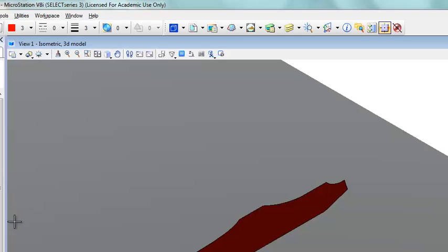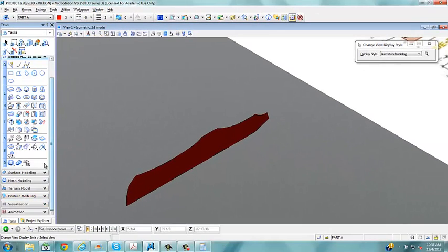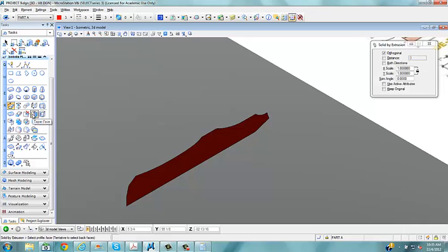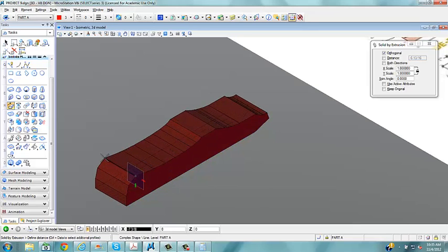So what we need to do now is extrude this. We're going to go to our solids modeling toolbox now, and under the R menu is our extrusion tool. The first one is just extrude solid by extrusion. So we can take any shape and we can extrude it orthogonally. And you notice the scale says XY is going to stay at 1, so it's not going to reduce anything. Just left click on any edge and pull this out. Now the thickness of this board for part A is, I'm going to say 3/4 of an inch. So we'll just type in 0.75.